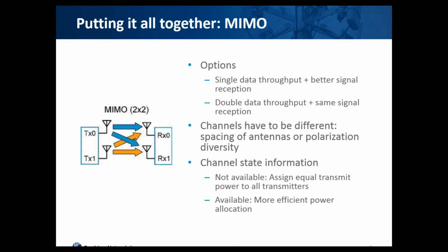For example, we can use space-time coding to send waveforms from each antenna, as we saw before. The advantage now is that we also have two receivers, so the signals received by the two receivers can also be combined using a switching technique, selection, or combining, as we saw for the SIMO systems, to make the received signal more robust. But a MIMO system can also be used to send more data.